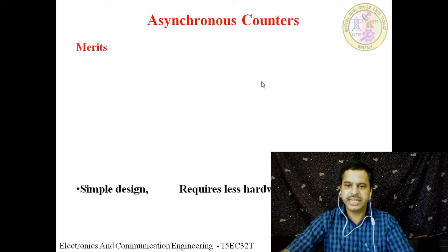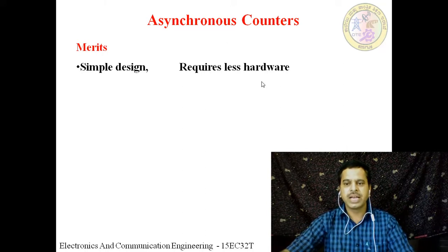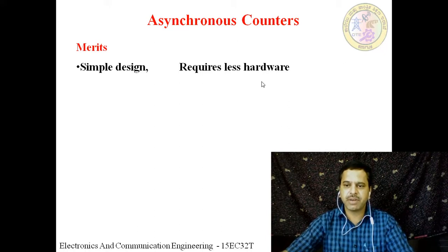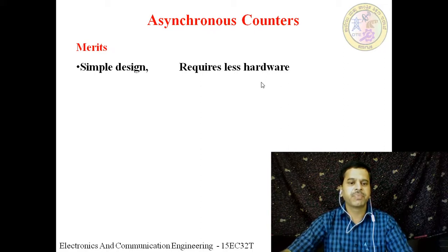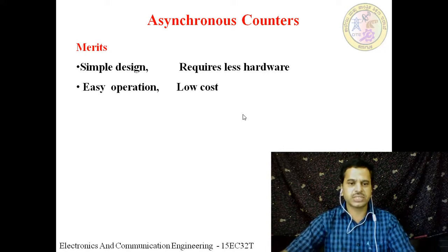So, what are the merits of the asynchronous counter? Simple design, because the output is given to the clock input of the succeeding flip-flop, and the next flip-flop gets its clock from the output of the previous flip-flop. So it is a simple design. It requires less hardware. We do not require much additional hardware, so it is easy to operate and low cost. The cost is also less.